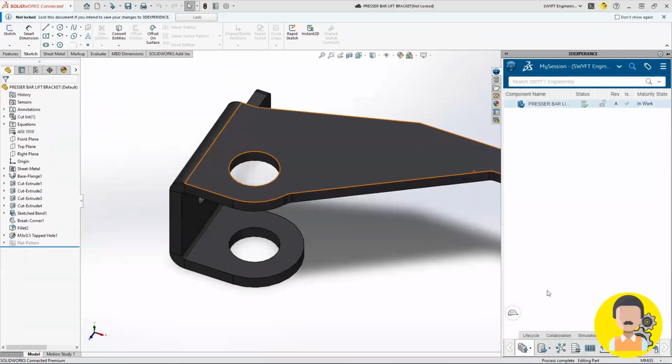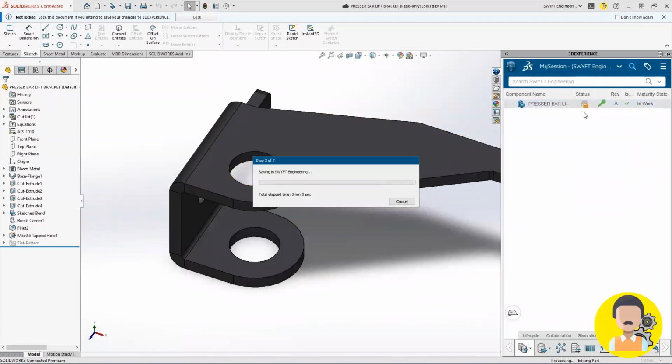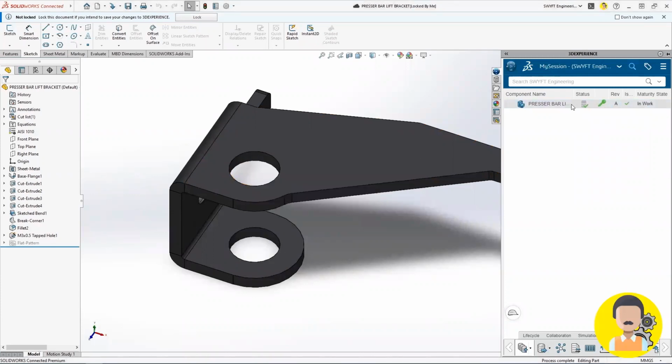Now, with data management, you can add a second layer of part numbering. So whether it be serial numbers, or in the case of 3D Experience, it's called enterprise item number, you can keep that generic description and title there, but you can add a second layer of part numbering once you get something to production, so that you have two layers of searchability. You can search that original descriptive title, or you can search that part number. So we have Lucas adding a part number here to this part. Now we'll go ahead and check that back into the system.